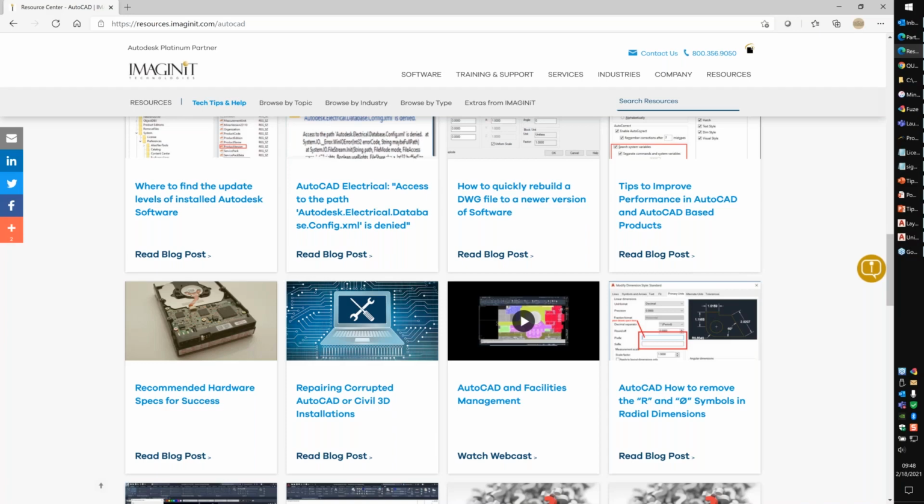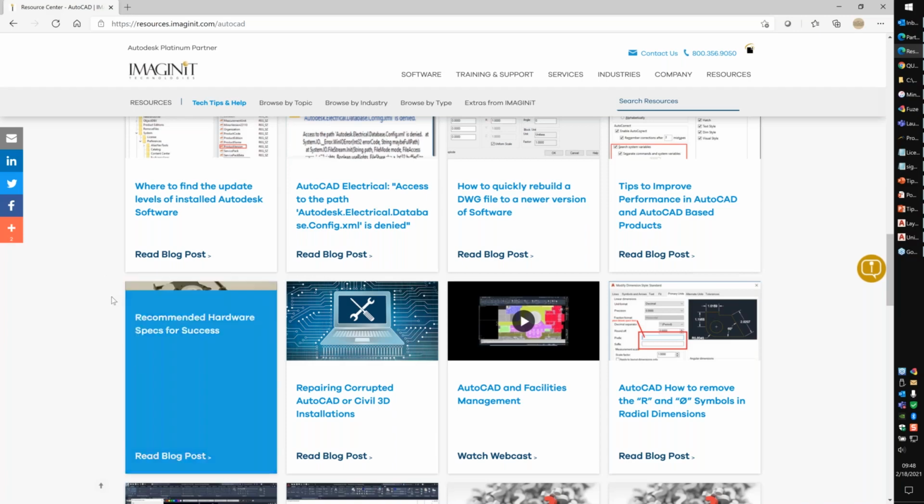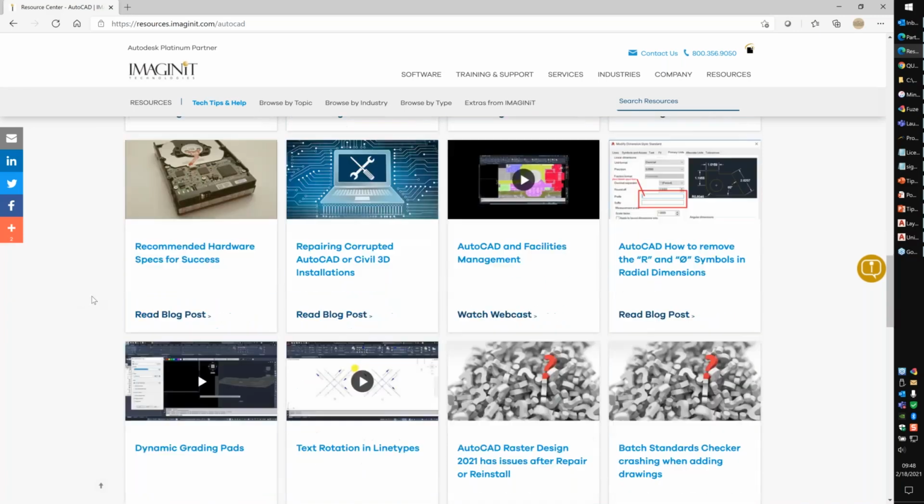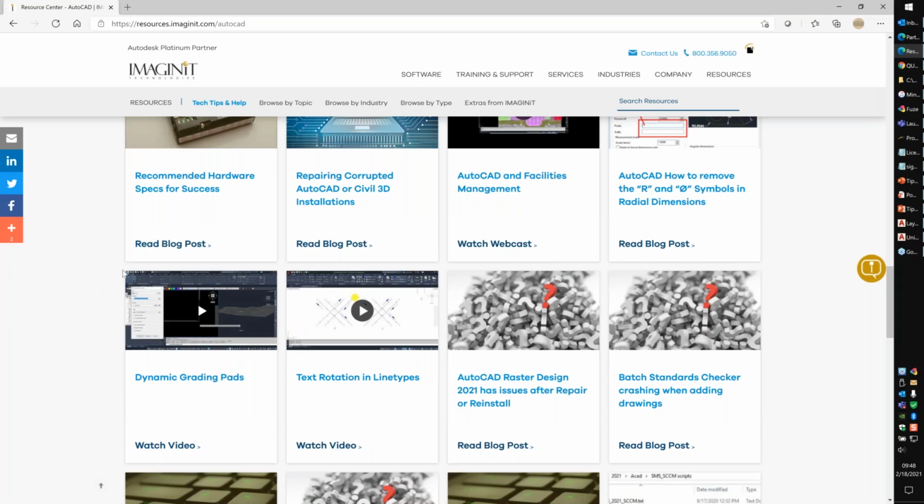Any recommendations on where to learn how to create isometric drawings? I don't have any off the top of my head, to be perfectly honest with you, because there's not a lot of people who are doing that these days. What I would recommend is that if you don't need AutoCAD and your Mac environment at the same time, switch over and use Boot Camp. You can definitely use YouTube for isometric drawings. There's a couple of settings in AutoCAD where you can change your drawing lines to go isoplane top, isoplane left, right, etc. to help with some of that.